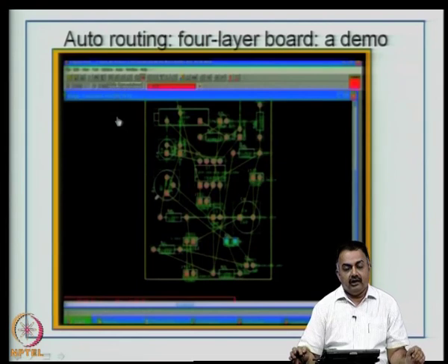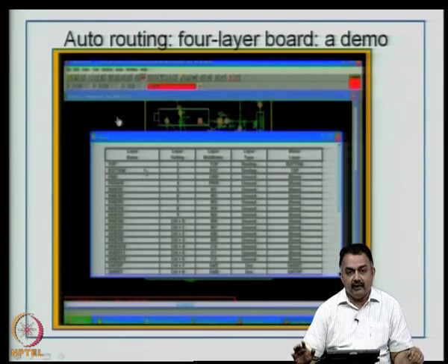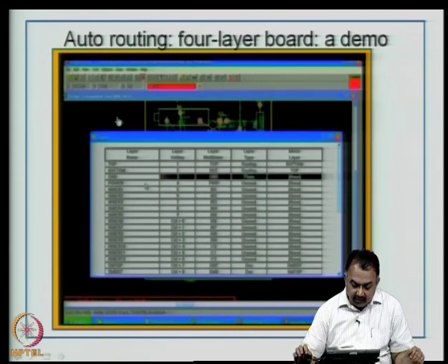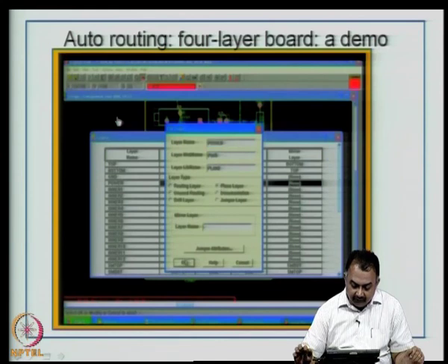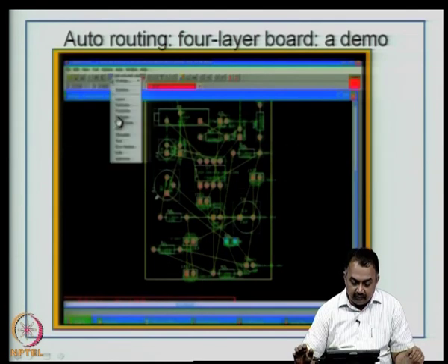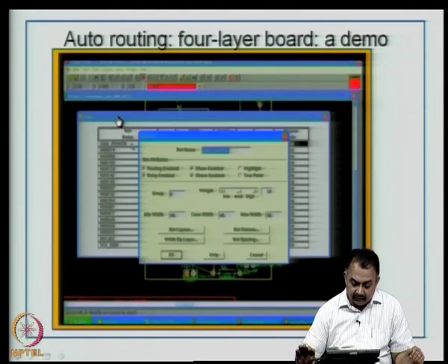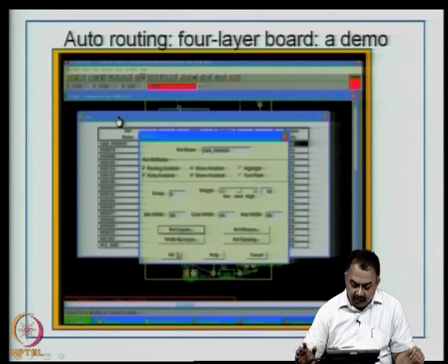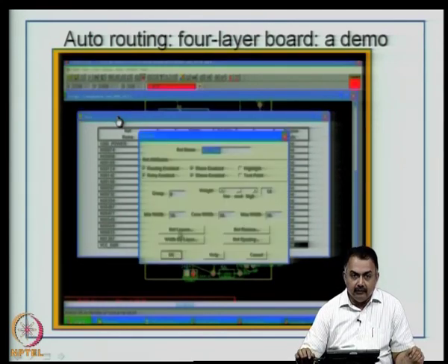the important thing is now you have to visualize a 4 layer board, a top electrical layer, a bottom electrical layer, then you need to have a ground plane. So, you activate the ground plane that is required to be inserted, and then a power plane, which is again not considered an electrical layer. So, it is considered as a plane layer. So, you can also set the design rules, that is the line width to be used in those areas, and you can also name this particular layer as ground power and so on.